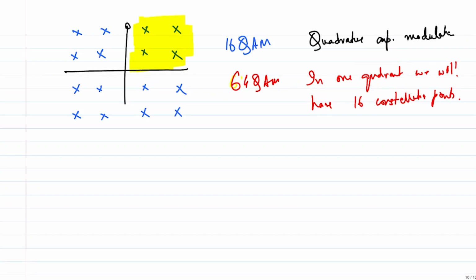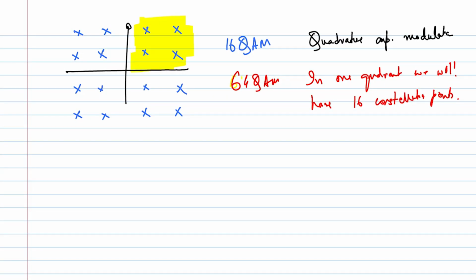Which essentially means that your signal-to-noise ratio requirements in your transmitter will be higher if you are using a denser constellation, compared with another constellation diagram which is less dense. So that is something you should also keep in mind, right? There is a trade-off the moment you try to pack in more and more symbols within the finite amount of power supply that we have.